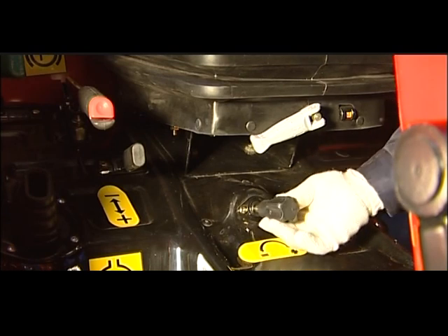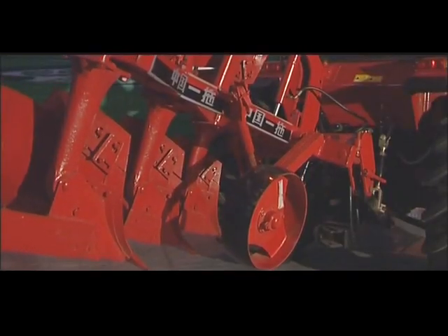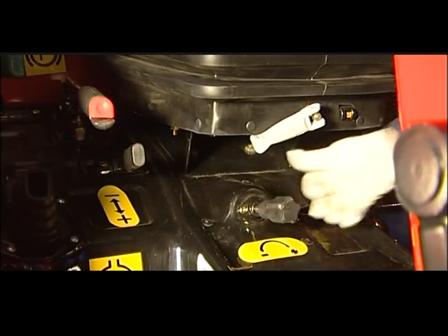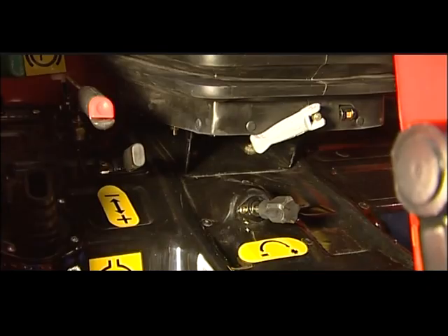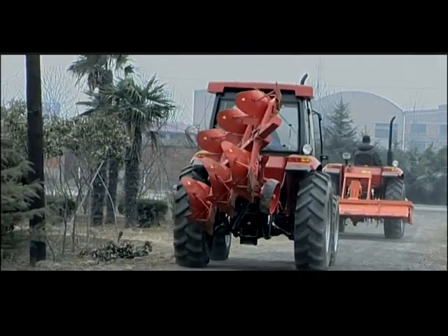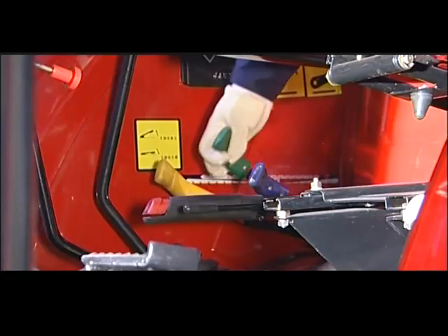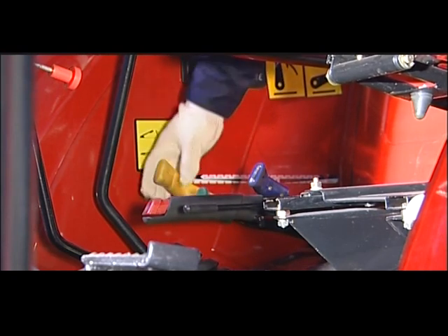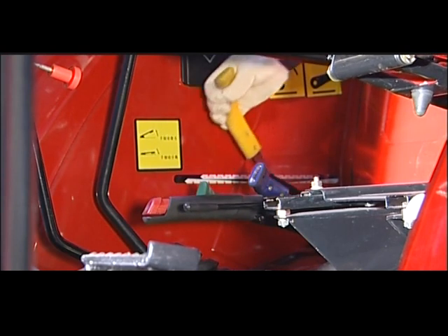When you turn the knob anti-clockwise, the farming tool coming down speed becomes slower. When you turn the knob anti-clockwise to the maximum position, the farming tool is locked at the desired height. At this time, even if you operate the force and position control levers, the farming tool will not go up or down.